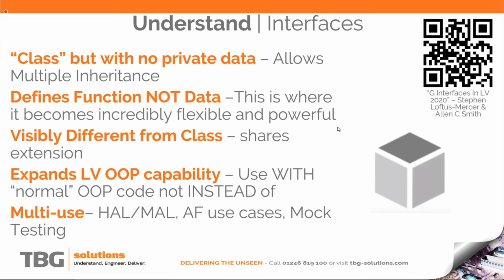But the key thing to remember, because I approach interfaces from a pure LabVIEW perspective, not from text-based programming languages, is something I didn't really grasp until looking at the design documents. What we're doing with interfaces is defining the capability or the function. We're not defining what data needs to be used. I've got a slide in one slide's time that visualizes that a lot better than I could ever explain it. It makes things really flexible and very powerful, especially from a hardware abstraction perspective.